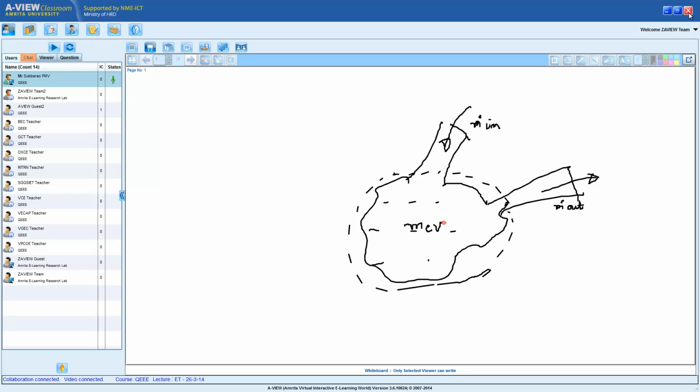Now the mass of the control volume can increase or decrease, satisfying the conservation of mass. Unlike a control mass, where mass cannot enter or leave, so the mass cannot change. In a control volume, mass can enter and leave, so whatever mass enters can get accumulated. Maybe the mass entering is much less than the mass leaving, or the mass entering is much higher than the mass leaving.